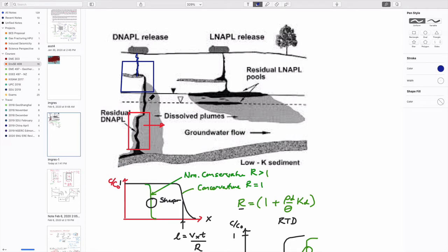And so some of it potentially will get hung up in here, in this chimney that we've talked about, which is present at maybe relatively low saturation, and in this lens that might capture it based on low permeability or high capillary entry pressure behavior to cup a lens here that will hold it in higher saturations.